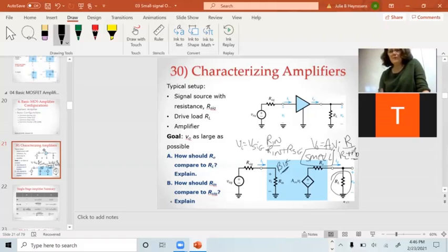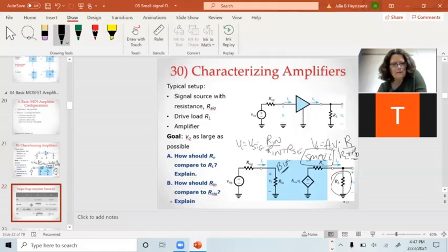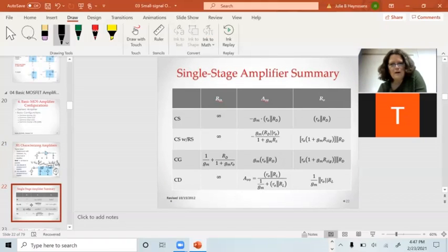And you see people like at Microchip trying to design ADCs that have analog interfaces to the real world, and they don't even specify what their RO is. And you just know it's bad because your circuit doesn't work. And if I put a larger load resistor across there, suddenly it magically works. Okay, real world stuff. They don't spec it. They're digital engineers, they don't know.